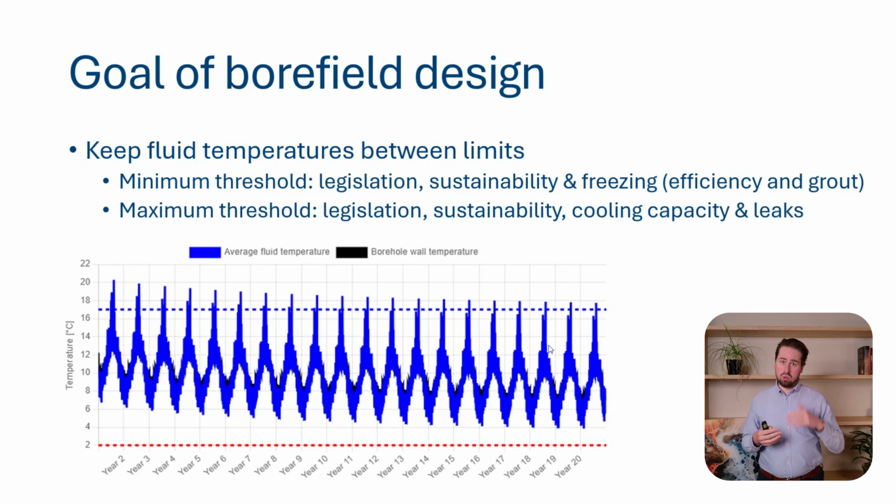But also if you go to too high temperatures, 40, 50 degrees, for example, there starts becoming a problem that the mineralogical structure of the ground starts to change, because some minerals start to dissolve in warmer water, and your geological condition is basically changing, which is also not something you want from a sustainability point of view, where you want to limit the impact you have on the environment.